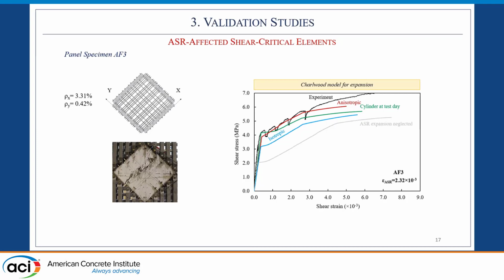Here are results neglecting the ASR expansion and deterioration. What I want you to observe here and remember is that if we neglect the ASR expansion and deterioration in our modeling, we end up with a much larger interval between the cracking strength and the ultimate strength that we calculate. And so this may be a problem.